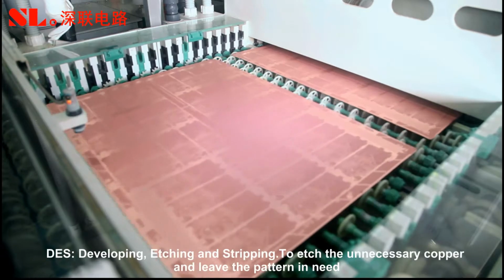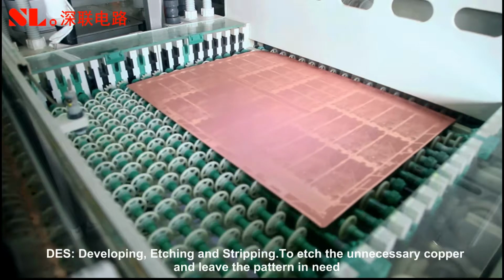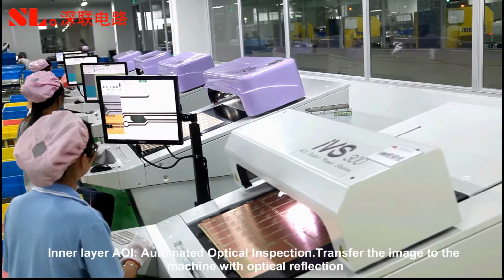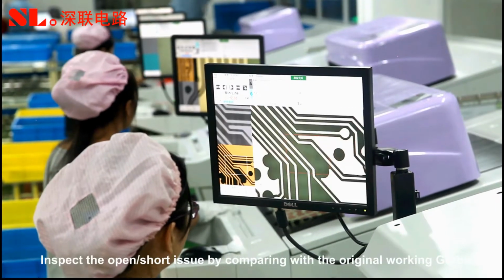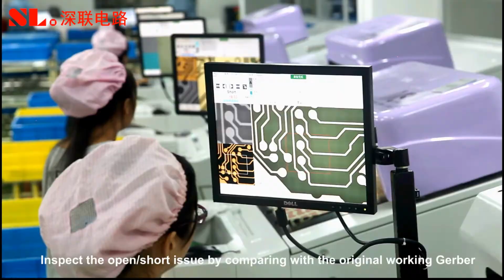DES, developing, etching, and stripping. To etch the unnecessary copper and leave the pattern in need. Inner layer AOI, automated optical inspection. Transfer the image to the machine with optical reflection. Inspect the open short issue by comparing with the original working Gerber.